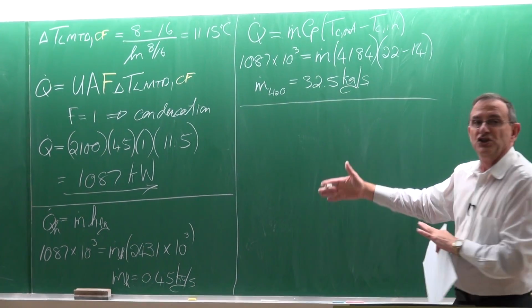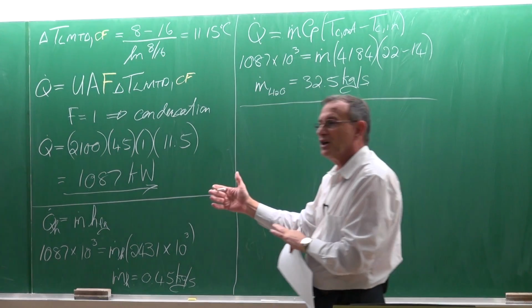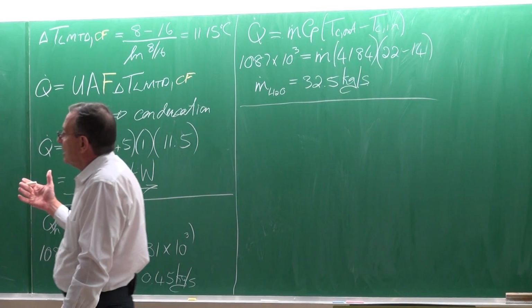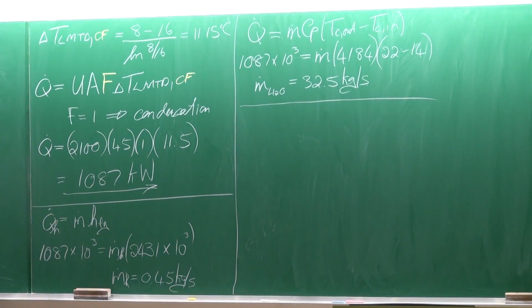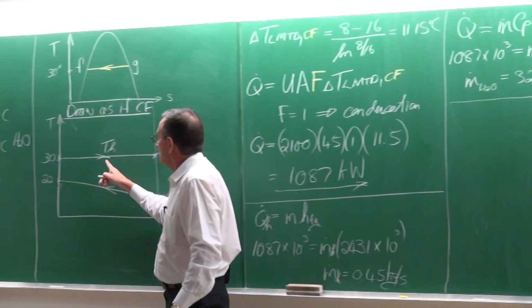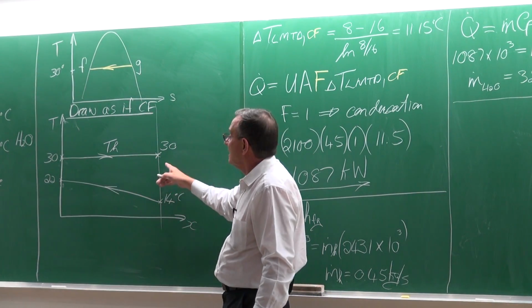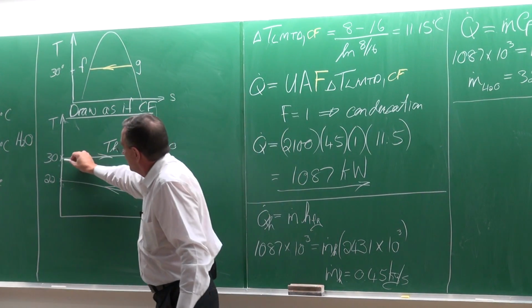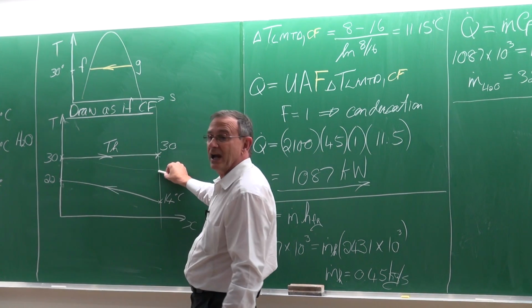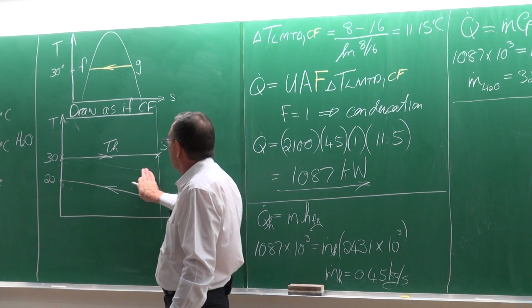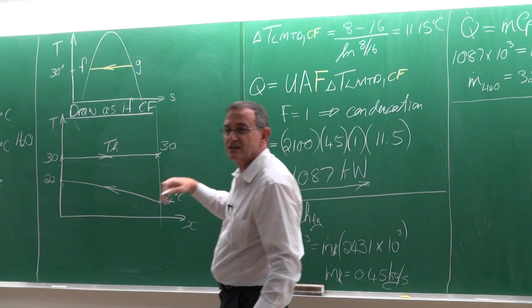I've previously mentioned how important it is in heat exchangers, that the best type of heat exchangers are normally when you've got a phase change. And what this now illustrates are two things. The one is, as I've mentioned before, your temperature remains constant. If it wasn't a phase change fluid, then this temperature had to do something like that. So your delta T would be lower. Okay, that's the first thing.